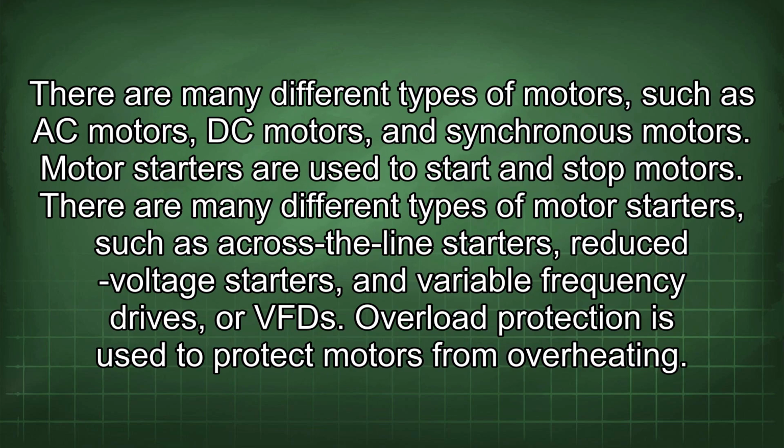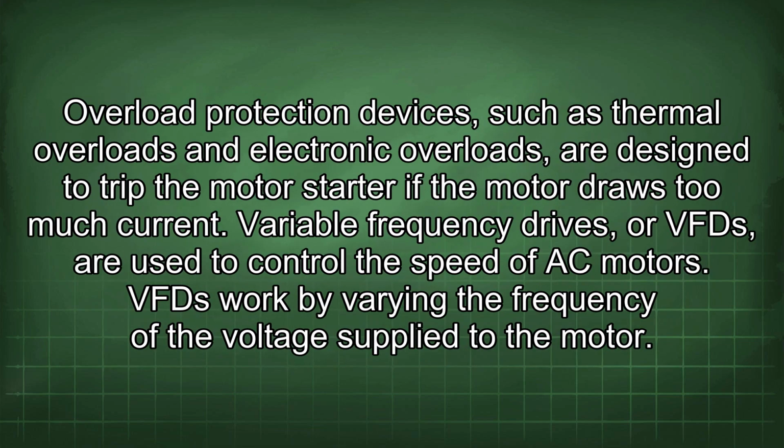There are many different types of motors, such as AC motors, DC motors, and synchronous motors. Motor starters are used to start and stop motors. There are many different types of motor starters, such as across-the-line starters, reduced voltage starters, and variable frequency drives, or VFDs. Overload protection is used to protect motors from overheating. Overload protection devices, such as thermal overloads and electronic overloads, are designed to trip the motor starter if the motor